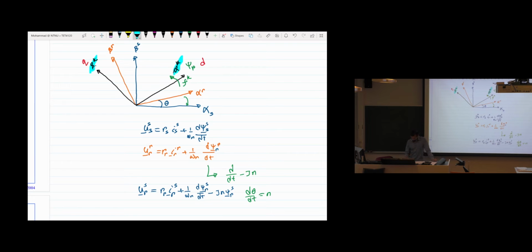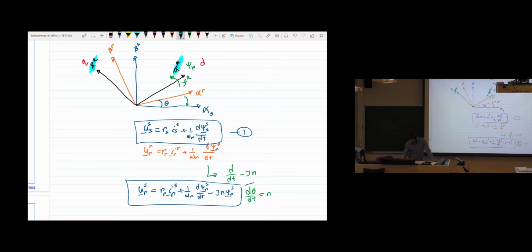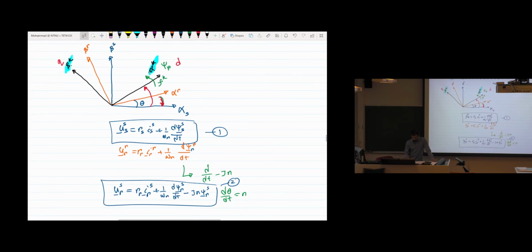So when we converted them to dq, now you have these two equations. The first one and the second one, these two. One thing you can see is that here we change the angle to this direction. Now we are putting it to this direction and it's rotating. If it's rotating in that direction, counterclockwise, then the derivative term here, we can represent this derivative term d dt, which is plus j f of s or f of k.